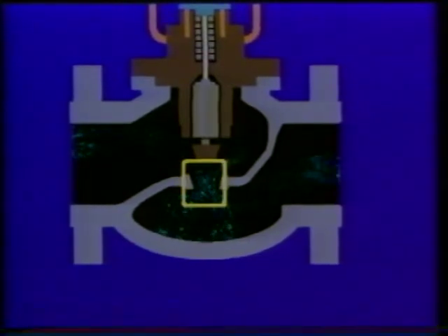Since the liquid passing through the valve port now contains vapor bubbles, the fluid density is reduced. Without a corresponding increase in fluid velocity, mass flow rate decreases. Effectively, the value C sub V is reduced. Fluid velocity can be increased by increasing the differential pressure across the valve. However, if the increased differential is obtained by reducing valve outlet pressure, the severity of cavitation will increase, and the effective value of C sub V will drop even farther.